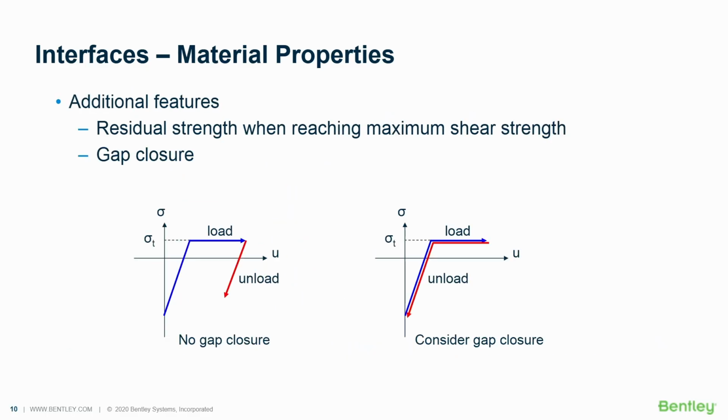I will not spend too much time on interface behavior in this presentation. I don't think that's the aim of this presentation, maybe just to mention that the interface elements have now been formulated considering a gap closure feature, which has been added quite some time ago, which enforces the interface to first close the gap due to opening through the tension cutoff before being able to retransmit normal forces from the soil to the structure and vice versa.